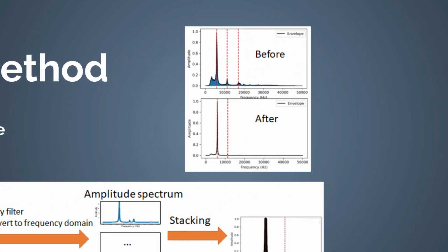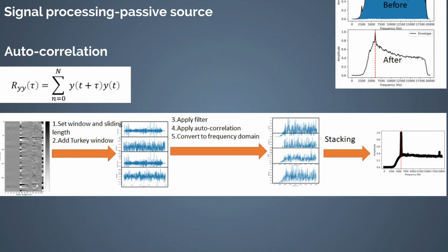Comparing the amplitude spectrum before and after implementing our data processing method, we identify a significant decrease in the low-frequency component. This observation suggests that the main origin of the low-frequency signal is likely due to external influence, such as the equipment or operator-related disturbance, rather than being inherent to the test sample.